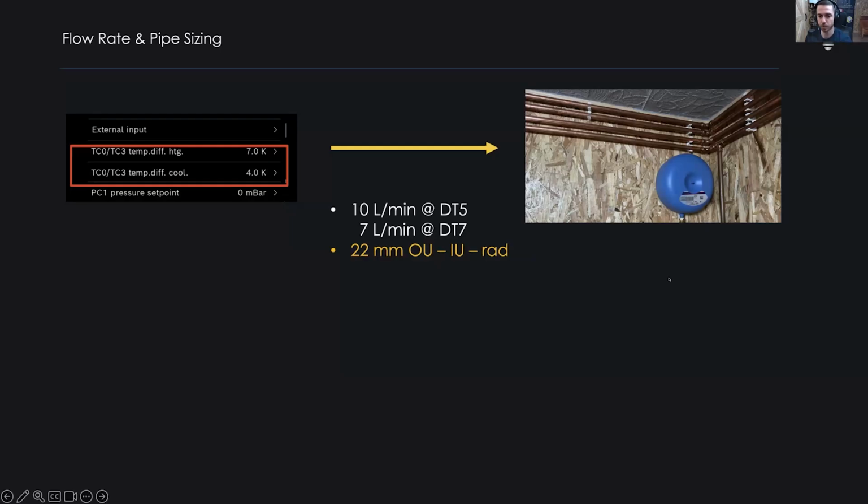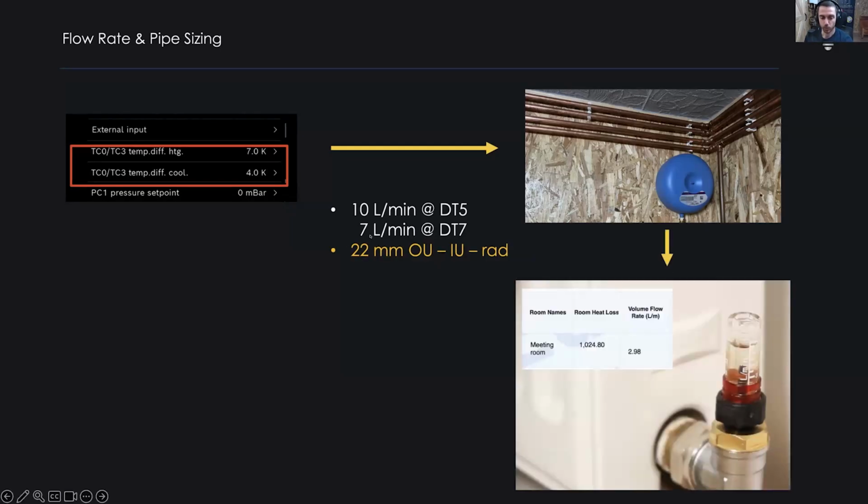And then after you are done with the heat loss calculation and pipe sizing, you need to calculate each radiator. Each radiator has some heat loss, flow rate, and heat output. This is what I have here. This is the same as you have for underfloor heating. Guys from the UK will know flow regulating valves, and you can set up and balance every radiator to the heat that must be delivered.